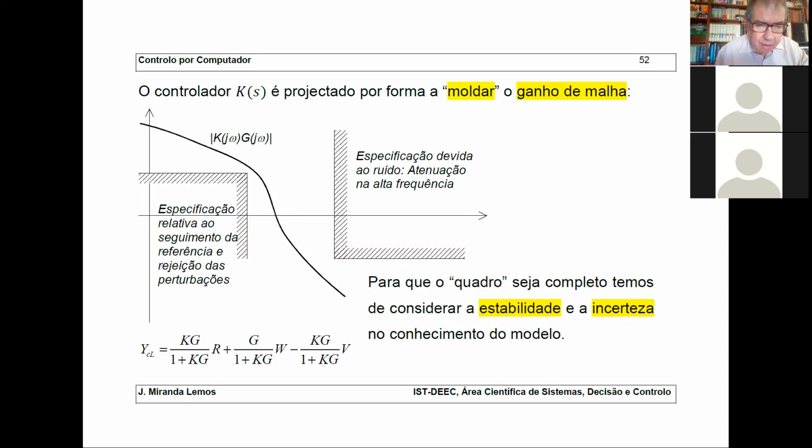That's a consequence of the Nyquist stability criterion, that is something that appears in your nightmares, okay? But for the moment, all you have to remember is that if you impose a very big, in negative terms, slope, a very fast decay of the loop gain curve, the phase drops very fast, and you have stability problems, okay?